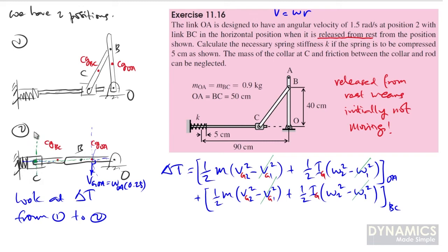So C happens to be our I location, and we know the velocity here will be equal to 0. The velocity at C will be equal to 0 since it behaves like our instantaneous center of zero velocity. The velocity at the center of rotation will be equal to 0. So straight away we know the velocity at C is equal to 0.